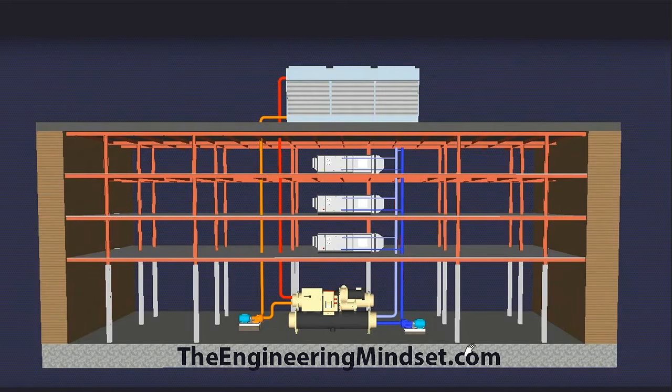Now, if you remember from one of the first videos I did on this channel, we looked at this kind of schematic here of how each part of the HVAC system is connected, and we looked at how the chiller here down in the basement, the AHU and the cooling towers, how they're all connected and what they're doing there. So we're going to be looking at this part here today, which is the AHU, the air handling unit, and that is what supplies the HVAC system, or conditioned air to the floor, or the floors, or the area within the building.